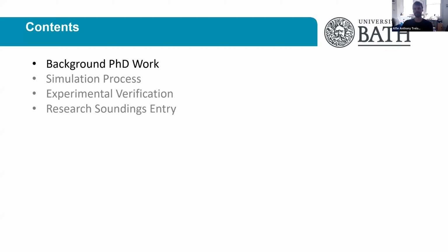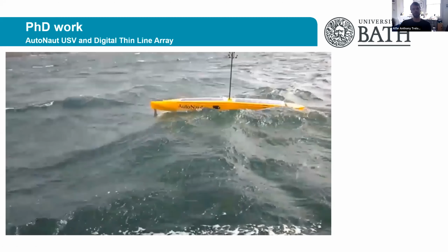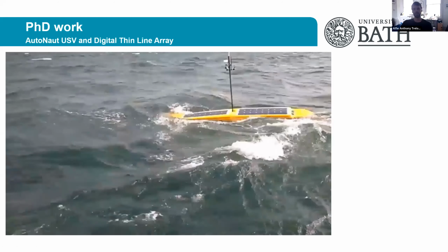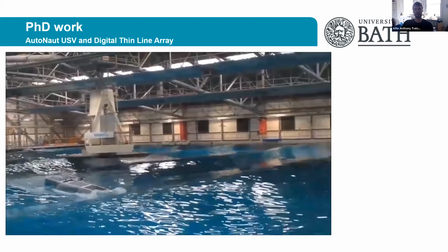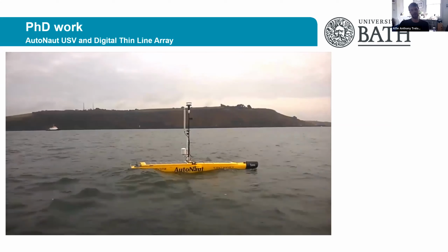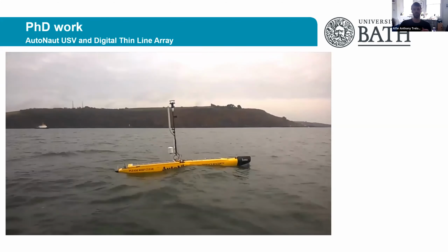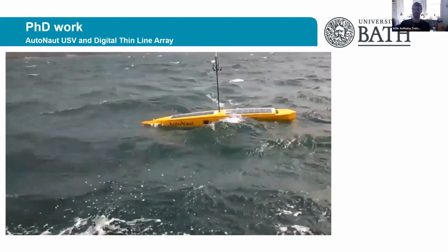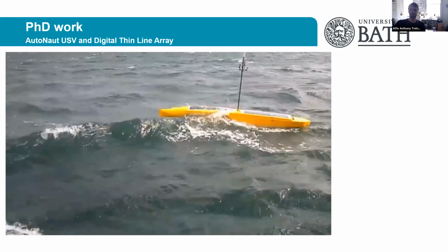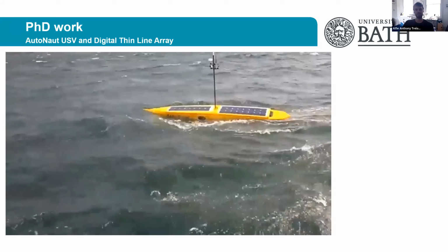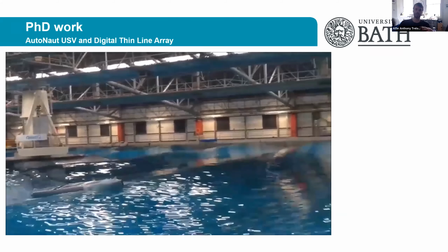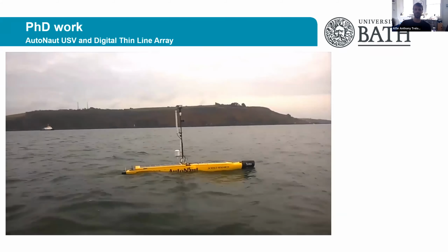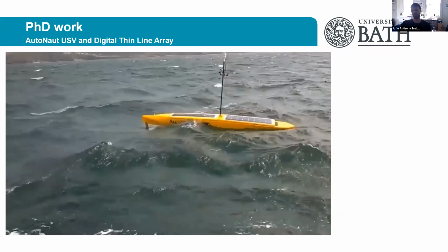So firstly, some background. My PhD work was focused on the use of passive acoustic monitoring techniques from an Autonaut uncrewed surface vessel, which is what's shown here in this video. And it uses a clever mechanism to directly convert hull motion from waves into thrust, even in the directional waves as shown here. And with the solar powered sensor payload, it's capable of extremely long duration missions, up to many weeks at a time. And also, being wave propelled, it has an extremely low acoustic signature, which makes it uniquely capable for passive acoustic monitoring purposes.